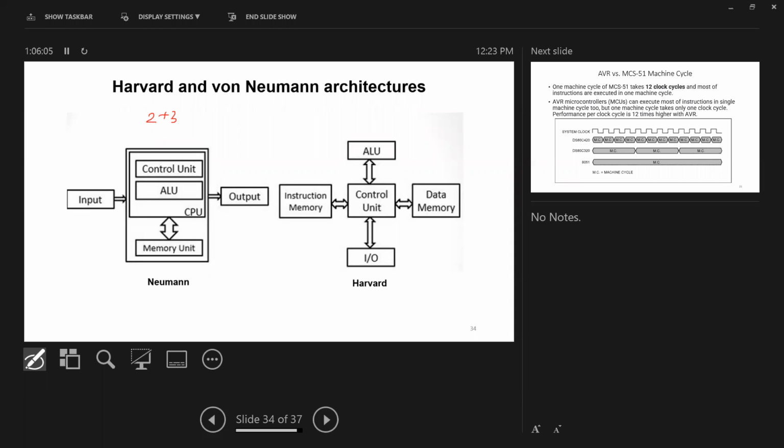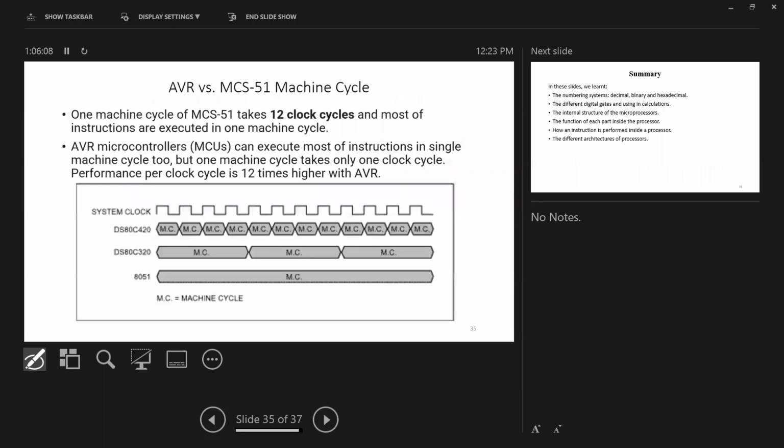So this means instead of having our instruction cycle moving for all of this long time, it would be less. So we have some processors that can consume less machine cycle or less time for machine cycle, like, for instance, this family of microprocessors. It can consume 4 pulses to execute 1 machine cycle. And we have some more advanced processors which can execute the overall process of an instruction cycle in just 1 clock cycle, guys.